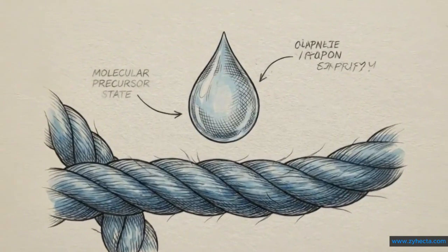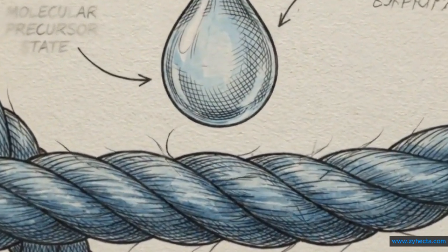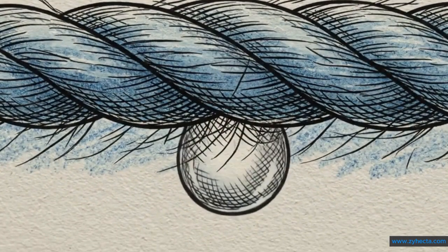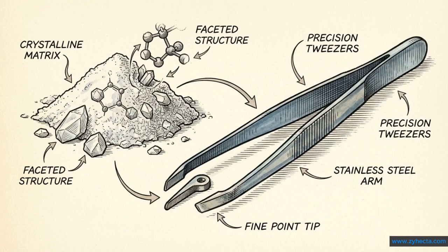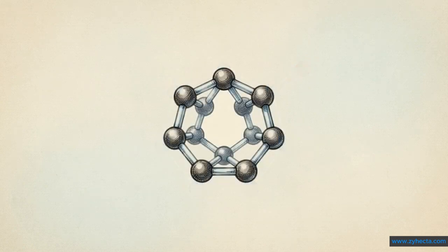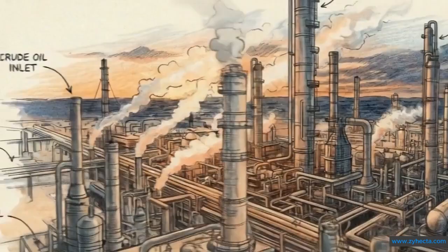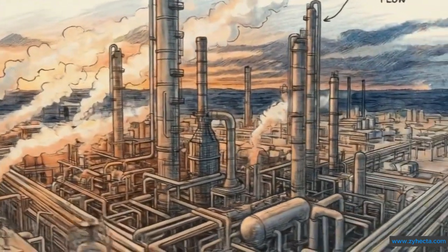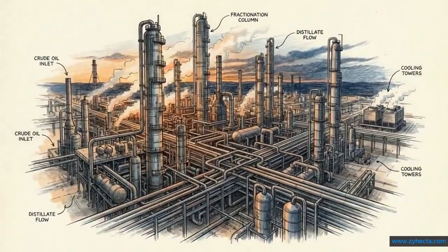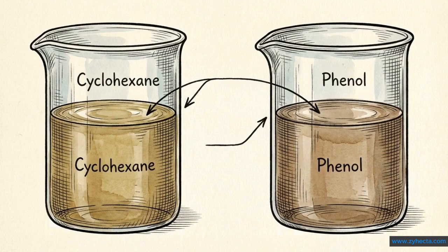But before a single thread of nylon can be spun, the production pipeline relies on a single chemical precursor, a molecule called caprolactam. In its raw form, caprolactam is a white, water-soluble solid. Chemically, it's classified as a cyclic amide, a molecule where the atoms are bonded into a closed loop. The industrial synthesis of this specific molecular ring is what provides the building blocks for the nylon 6 used in these heavy-duty applications. Building that ring starts with basic hydrocarbon liquids, usually cyclohexane or phenol.